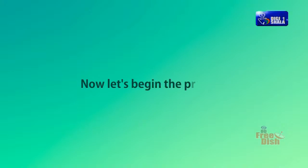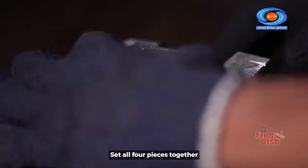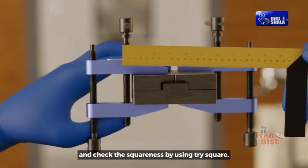File the parts to its size and shape. Now, let's begin the process. Set all 4 pieces together and clamp them with parallel clamps and check the squareness by using a tri-square.